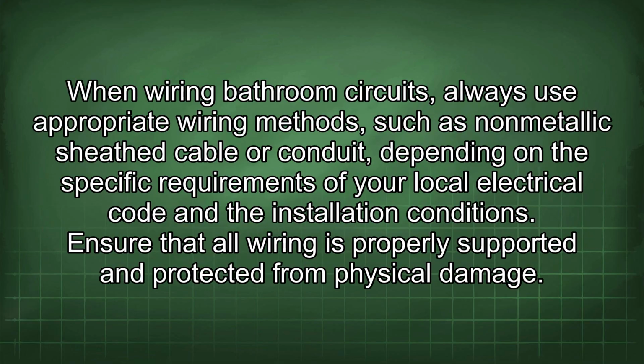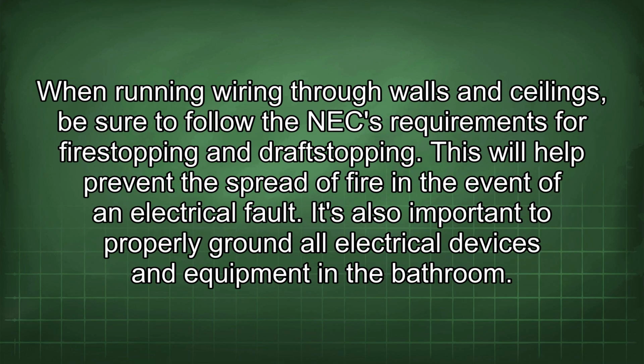When wiring bathroom circuits, always use appropriate wiring methods such as non-metallic sheath cable or conduit, depending on the specific requirements of your local electrical code and the installation conditions. Ensure that all wiring is properly supported and protected from physical damage. When running wiring through walls and ceilings, be sure to follow the NEC requirements for fire stopping and draft stopping. This will help prevent the spread of fire in the event of an electrical fault.